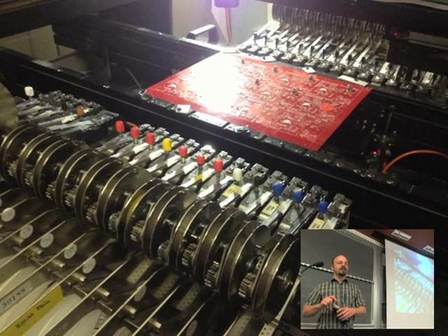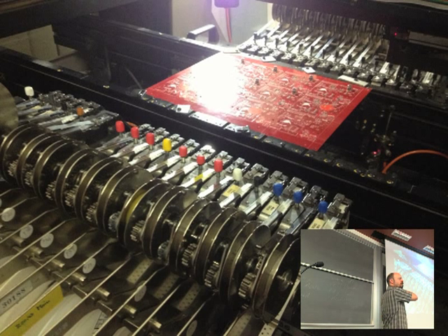There is solder paste. So instead of putting solder on or just putting the parts on top of it, I actually left a step out in here. And that's the screen printing. What happens is there's solder paste that gets put on top of each and every pad. And solder paste is basically liquid solder that has resin in it and solder to solder it together. Gets put on there, and then the parts get put on top of this solder paste. And the solder paste is actually good enough to hold the parts in place without any problem. So there's enough friction and contact surfaces that they just stay there.